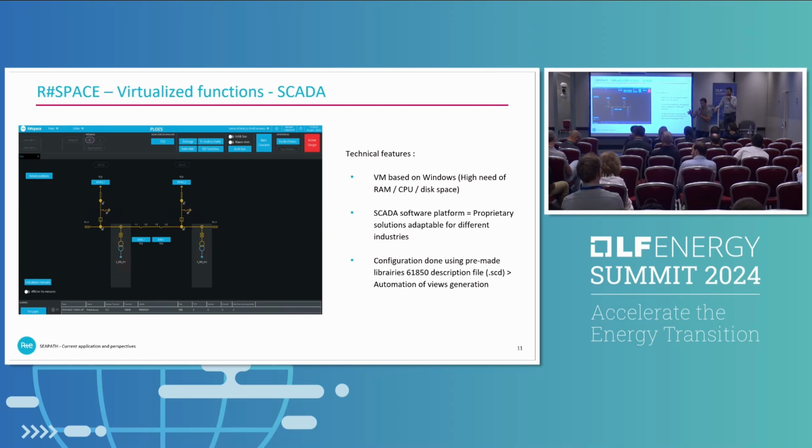But yeah, right now, if you want to have SRIOV, you wouldn't be able to host it in a substation that takes the sun too much. So that would be a problem. We have the same problem with RAID hardware. This is not about networks; it's about disk resilience. But we have the same problem with RAID hardware. If you buy a RAID chipset, a RAID adapter, some vendors have them. They won't support over 55 degrees. And if you want to keep 70 degrees, you can't use SRIOV. You can't use RAID basically.